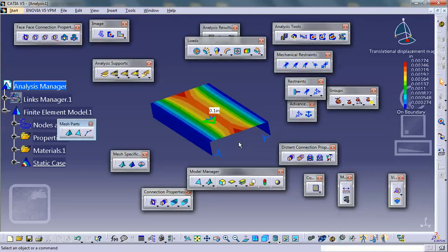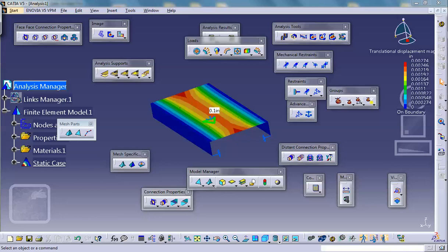Keep in mind that all planes of symmetry, you need to use them on the final exam. If you do not use a sufficient number of planes of symmetry, the proper number of them, you will lose marks. Please make sure you understand what this is all about, because I noticed that in the lab, in spite of all I said, people were still using solid elements to model the shell. People were still using the full model, and you're going to lose a big chunk of marks if you do that. Okay. All right, guys, let's move on.